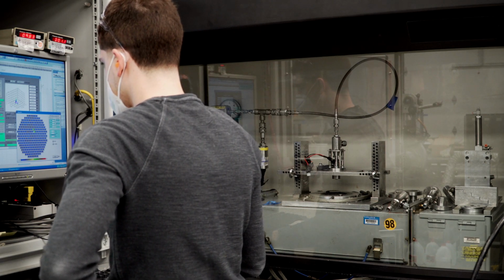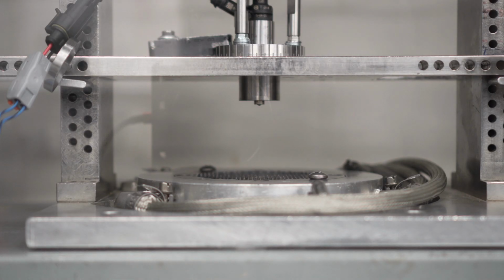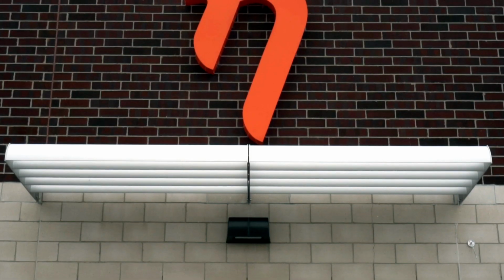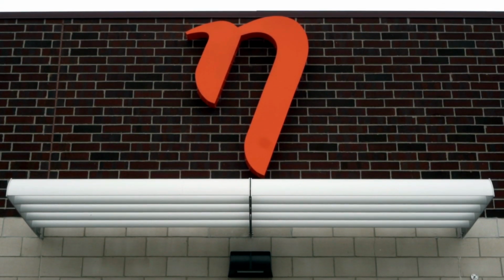The testing methodology for this equipment follows the SAE J2715 standard for spray characterization, and we are capable to run injectors from 3 bar to 345 bar, which covers the range used today for PFI and DI injectors. Another curiosity for this equipment is that it is available to only a few companies, and we are very proud to be one of them.